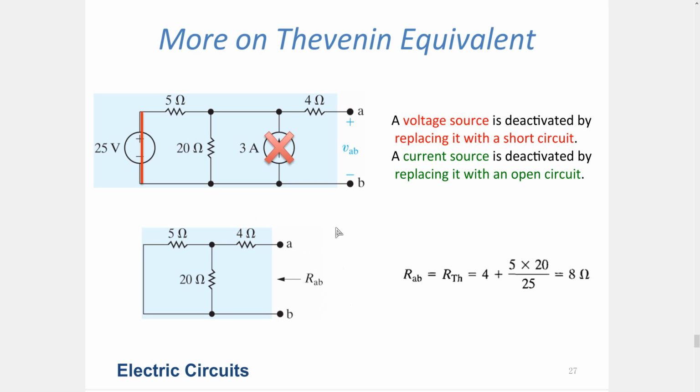Our purpose becomes finding VS versus IS, because that is the resistance basically, and that's the equivalent resistance, which would be the Thevenin resistance. We write down our equations and we try to find the ratio of VS over IS throughout the circuit equations. When we have that, it means I have found the RAB and I can model the behavior.